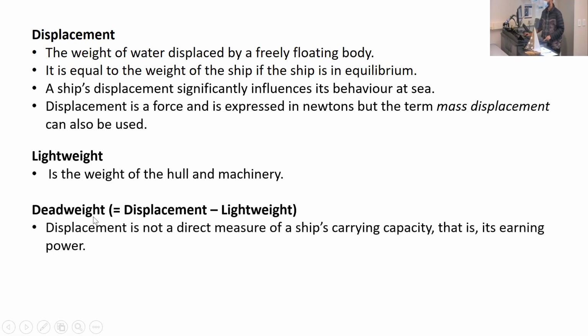It's basically what you're carrying on board: people, food, fuel, cargo. That's all contained here, dead weight. So it's total displacement minus hull and machinery.